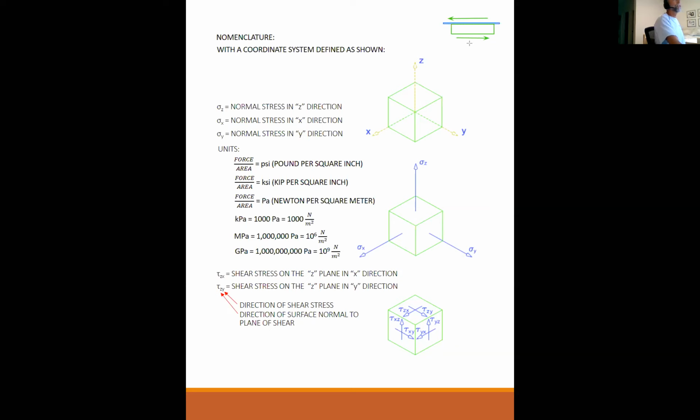It's not truly 100% shear because there's some eccentricity between these two, but it's as close as you can get. If you were to slice this open lengthwise and look at the stress, it's almost 100% shearing stress. There's no normal stress on it because you don't have any component of load going in the normal direction. So this would be pure shear. The other one was pure normal. And then of course you can have an infinite number of ways to get something in between.